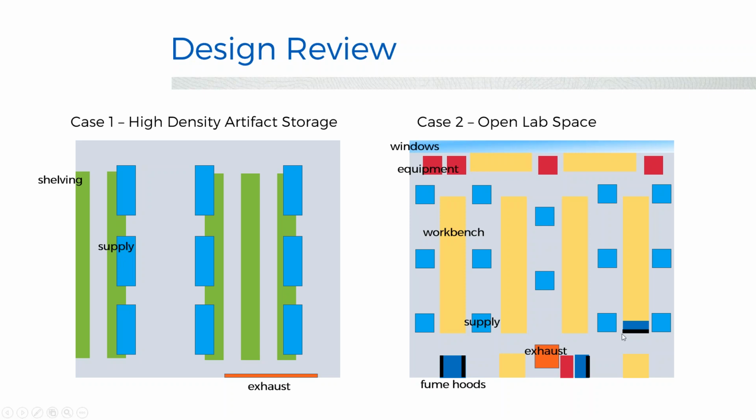The other thing we noted was that if they're looking at reducing air change rate, you have this fume hood with two swirl diffusers on either side. And if you remember from previously, when you reduce your air change rate, you need A, a lower temperature, and B, you'll have less momentum coming off your diffuser. So it is likely that in some scenarios, the plumes of air coming off this would drop and descend into the occupied space and would likely interfere with the containment of this fume hood. So we talked about either moving the diffusers further away from the fume hood or moving the fume hood so it wouldn't be impacted.